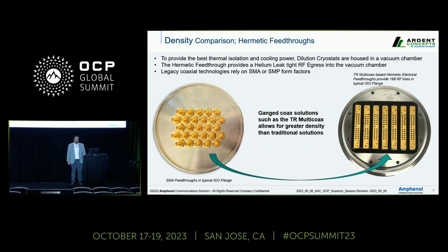In the image on the left, we see a hermetic electrical feed-through based on an O-ring sealed bulkhead SMA within a standard ISO flange. However, SMA feed-throughs have limitations and require generous clearances for tools such as torque wrenches to facilitate installation and removal of coax cables.